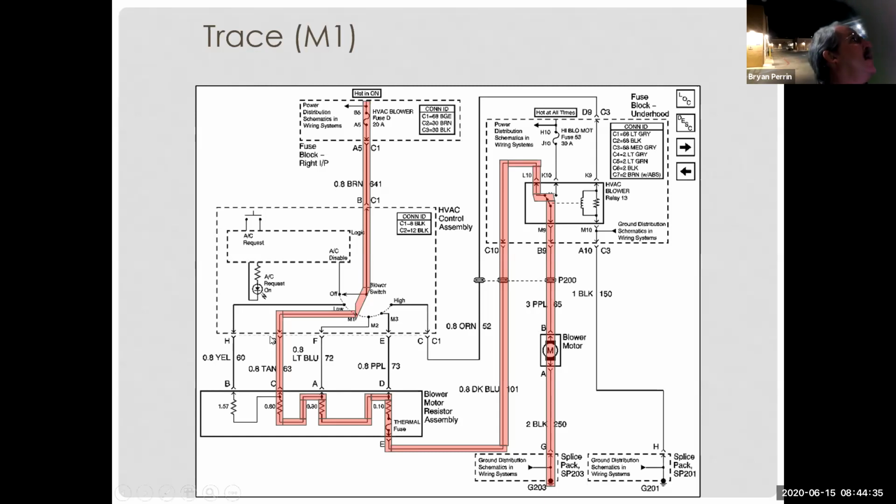Because if I'm on low, I'd have system voltage on B and it'd go less and less and less. I go to M1, now I got system voltage at 2 places. If I go M2, I'd have system voltage at 3 places. Wait a minute, what's going on here? I don't understand. Well, it's because I have all these open legs that just have potential. I'm not doing anything with the voltage, but it's still there.